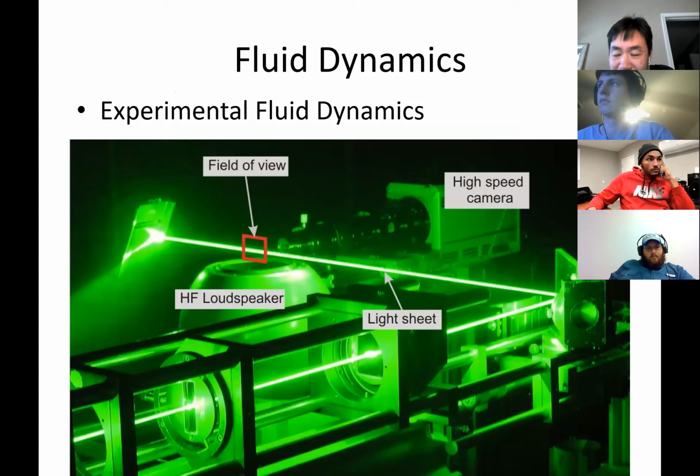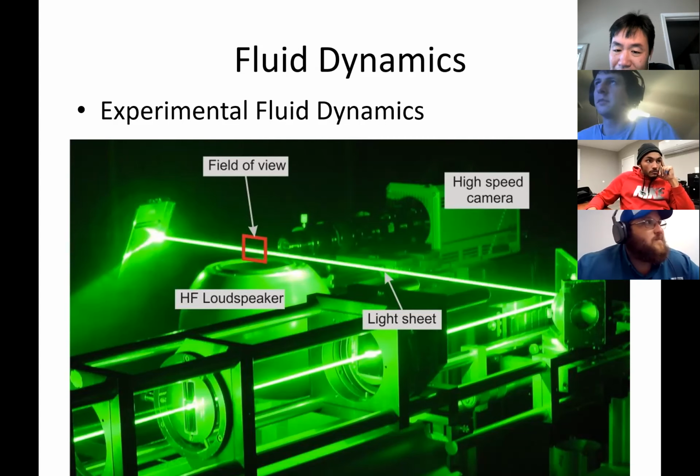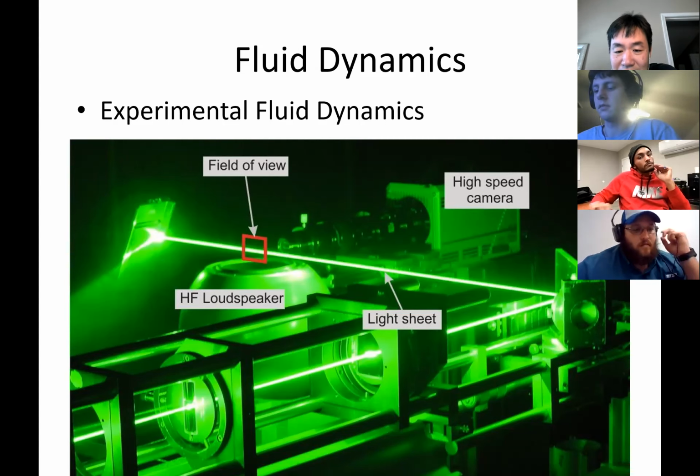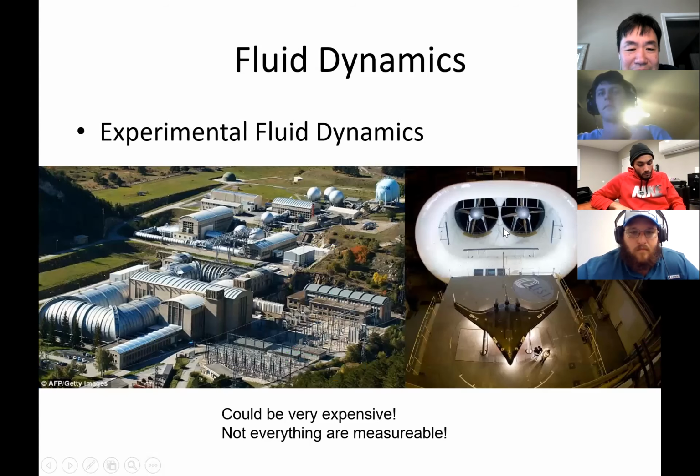The particles move and reflect the laser light, and sometimes they inject particles into the flow. You can track the movement of those small particles at different times by taking pictures. If you take pictures of the same particle at 2 different times, you know how its location changed, then you can calculate the distance, speed, velocity, acceleration, those kinds of things. It's very expensive and complicated.